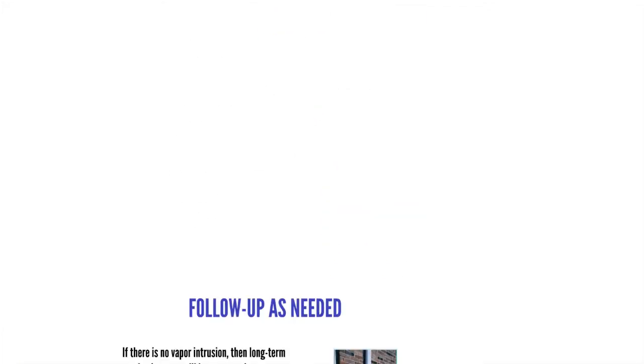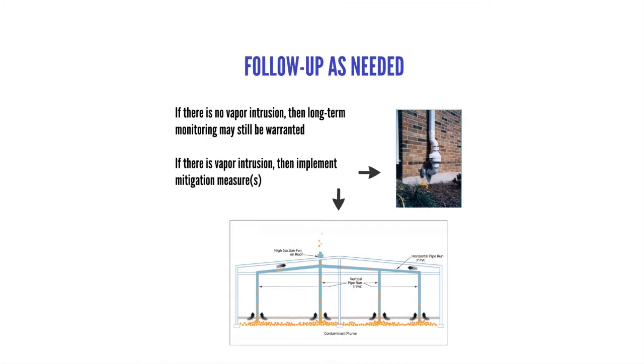Very cool. So if you find indoor sources, you remove them, and then you can test again without those sources. If you're below the screening level, then you move towards long-term monitoring. But if you're still above the screening level, that tells you that vapor intrusion is occurring from groundwater to the subsurface, and you need to mitigate that problem.